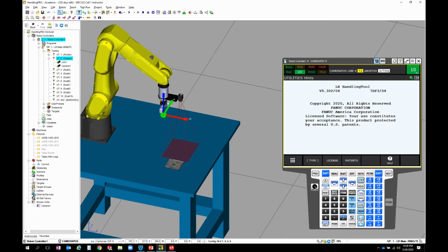The tool frame is in the same orientation, so I've got my positive Z going up and my positive X going forward. If we were just to do this with the normal 3-point method, our positive Z would actually be pointing downward. And so for this example, I don't want that. I want it pointing up. So for your lab 4, make sure that you have that oriented very similar as you would for the world axes or for the world frame.